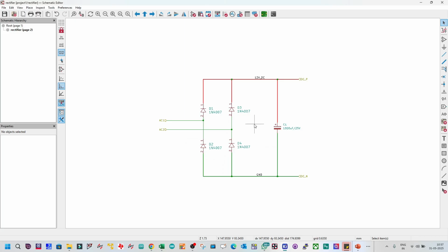So your question was whether this will be connected to other pages also. Is that the question? Yes, sir. If I am using another subsidiary, will the net name be the same or different? Yes, it will be the same. Let us say you have used 10 instances of this same block, and if you make any changes in one block, it will be replicated to all the blocks. I will come to that point and show that.